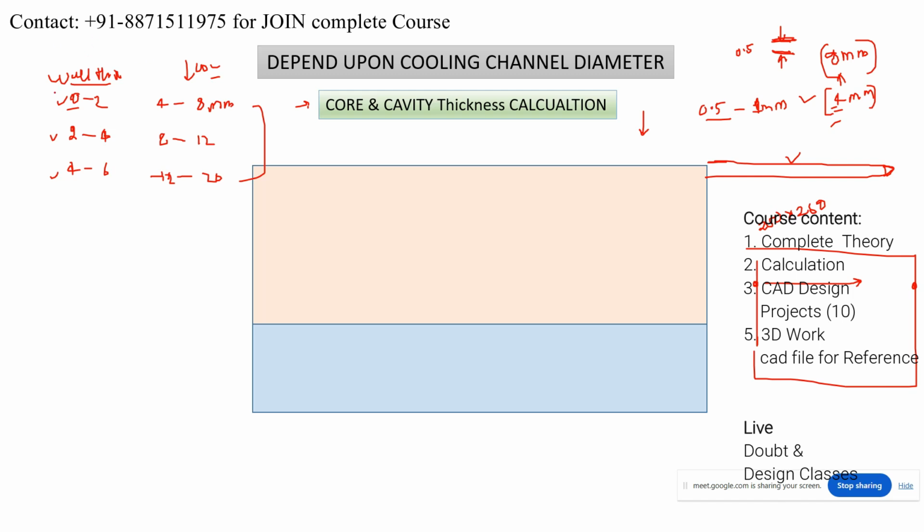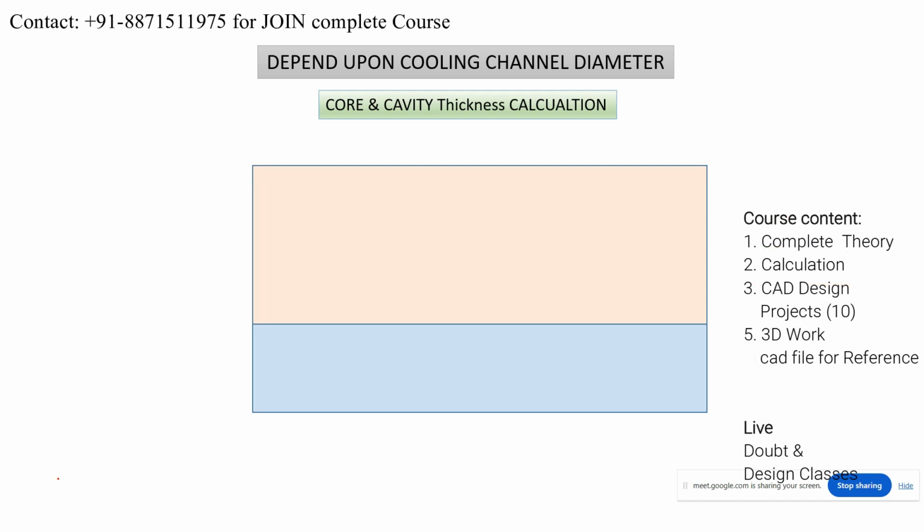Okay, so that's why if your wall thickness is from, for example, 0.5 to 2 mm, you have to select 8 mm or 10 mm for manufacturing feasibility. It should be feasible for manufacturing, right? Yes. Okay, so this is very important. Is it clear?